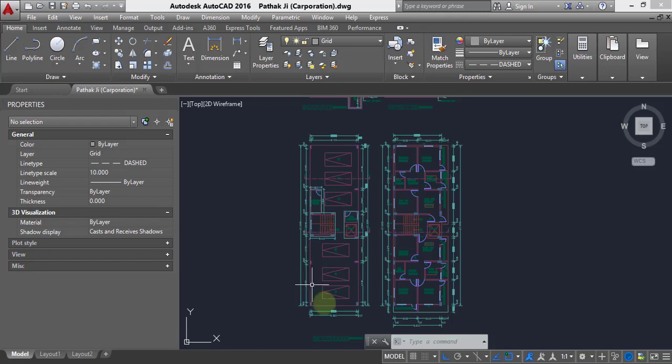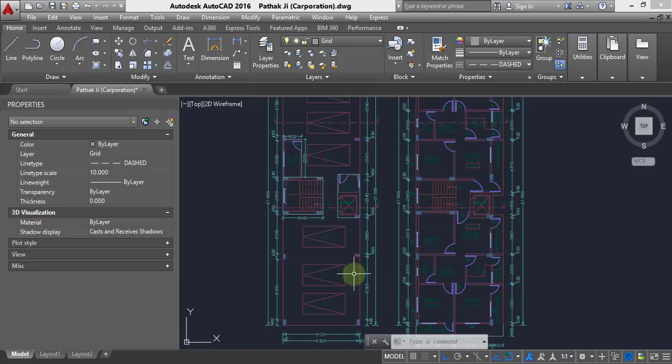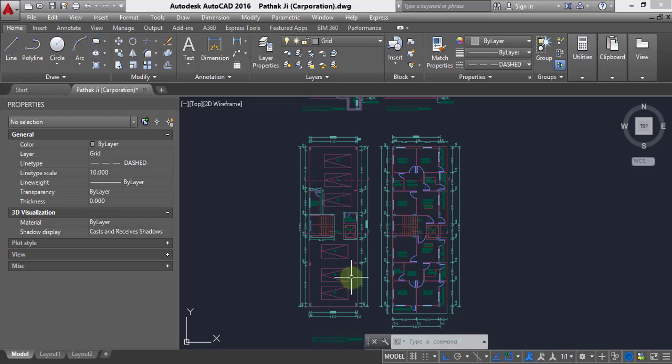Basically, what you will try to do is proportion the column dimensions, or check whatever column dimensions the architect has provided. For that, one has to tell what should be the total reinforcement which needs to be provided in the column. And also you need to design slab, you need to design staircase, you need to design roof beams at different floor levels. Then you have to design the footings also. So all those designs one needs to do.